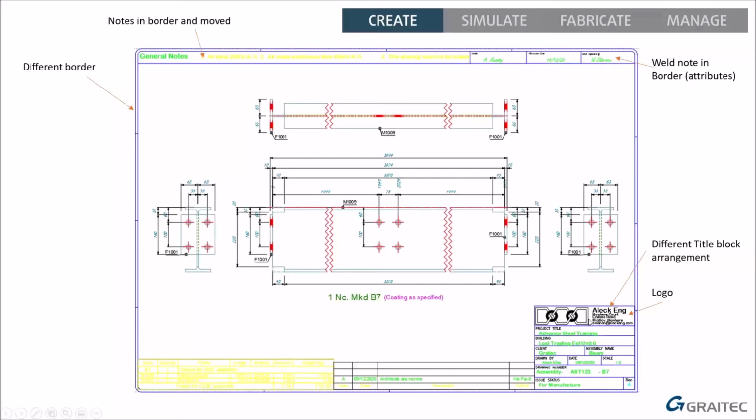I've also obviously got a different title block. I've got a completely different logo in there, naturally. I've included the approval status. I said I'd come back to that later. One of the tokens you can use is the approval status. So in Document Manager, you should be aware that you can pick the approval status on the right, select some drawings. On the right, it says not set. Change that to approved, rejected, revised. You can add your own entries in that using the Object Property Editor. So I've got for manufacturer showing here. So whatever you choose as the status on the right hand side of Document Manager, you can include that in your title block. It automatically gets written in if you put approval status as one of the tokens.